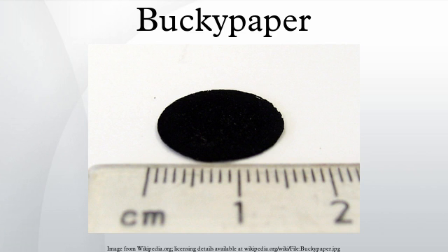Synthesis: the generally accepted method of making CNT films involves the use of non-ionic surfactants, such as Triton X-100 and sodium lauryl sulfate, which improve their dispersibility in aqueous solution. These suspensions can then be membrane filtered under positive or negative pressure to yield uniform films. The van der Waals interaction between the nanotube surface and the surfactant can often be mechanically strong and quite stable, and therefore there are no assurances that all the surfactant is removed from the CNT film after formation.